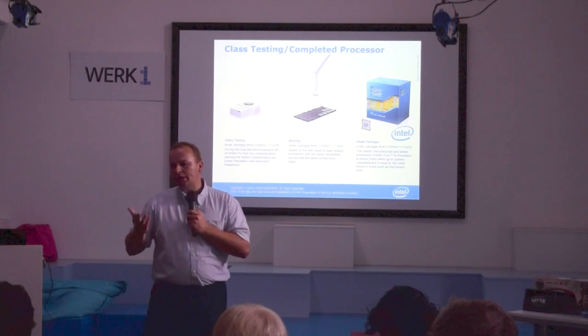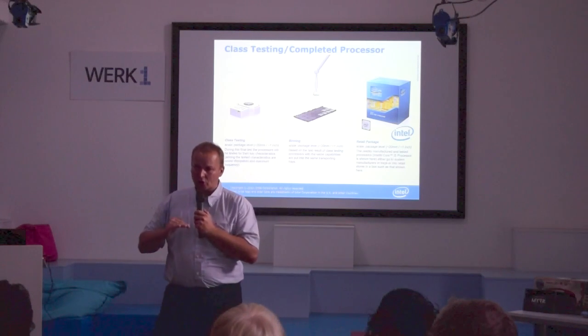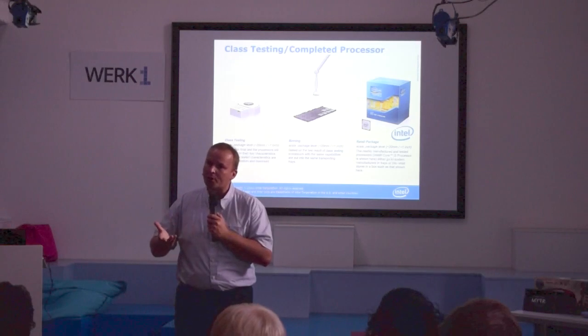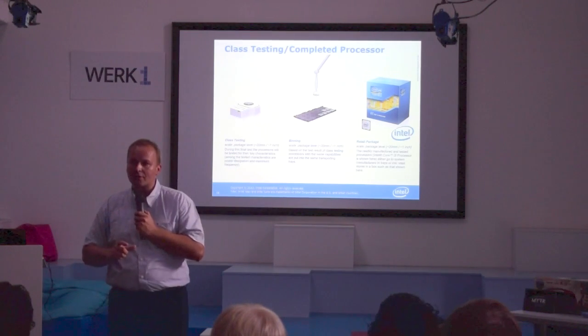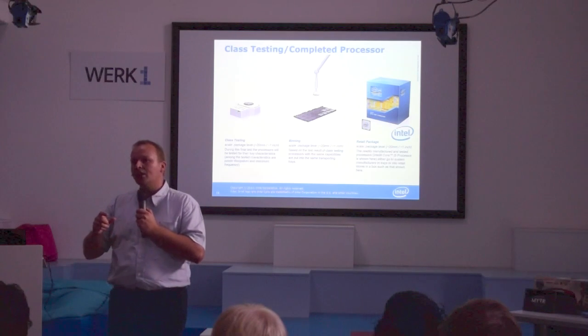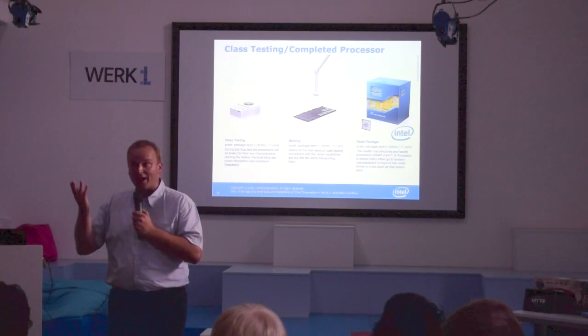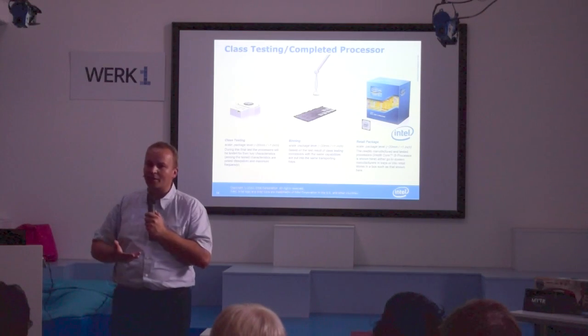No, the idea really is we always want to have perfect wafers, and sometimes manufacturing is tuned towards a certain goal. So for example, if we want to create notebook processors, then the manufacturing process is tuned towards low power consumption. And then what happens actually is you don't get a whole lot of processors that run at high frequency, but you get a whole bunch of processors that consume very little power.